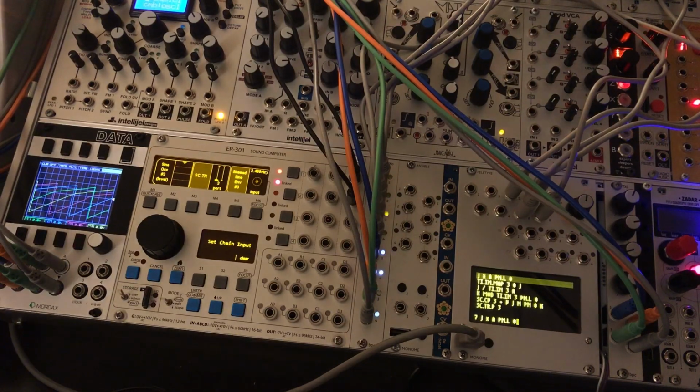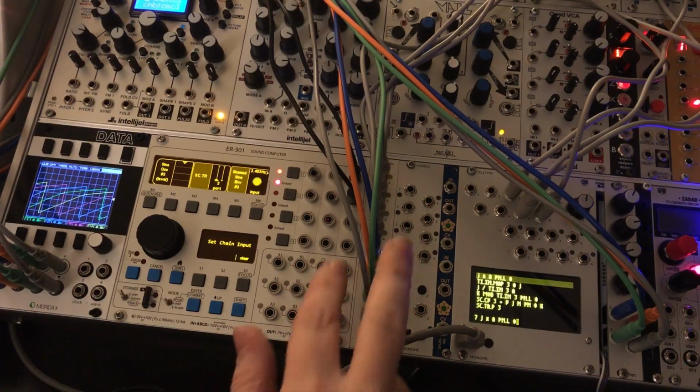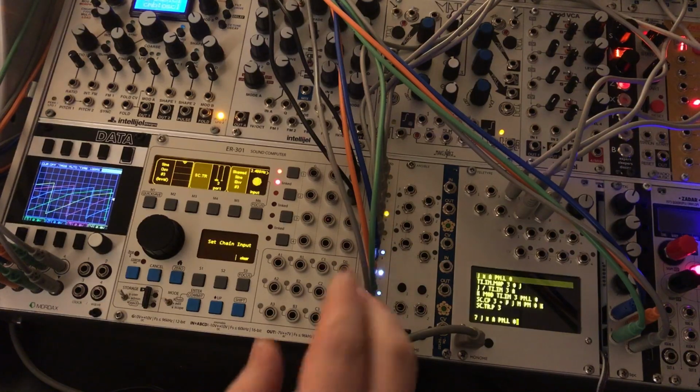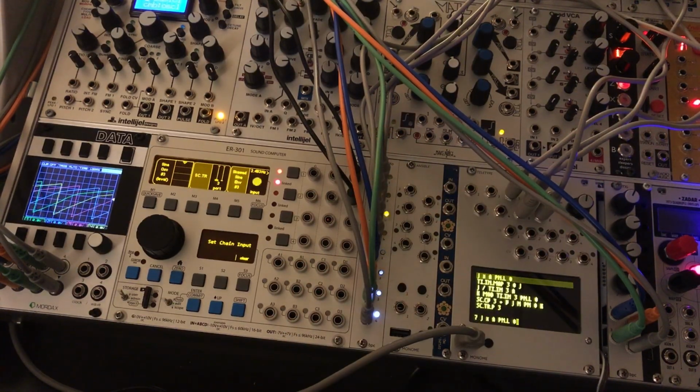All right, cool. I think that's about it. So in conclusion, what we've done here, we've set up the TXO to generate a quadrature wave table oscillator. We've set up the TR ports to generate 4 independent metronomes, over which we have some control over the tempo and the multiplier for each one individually.